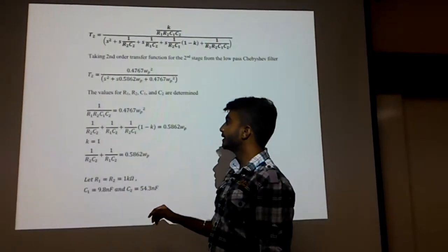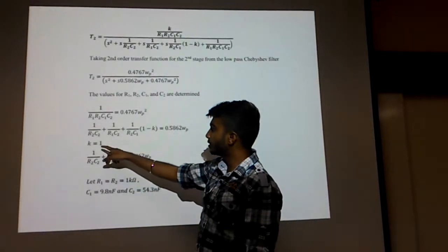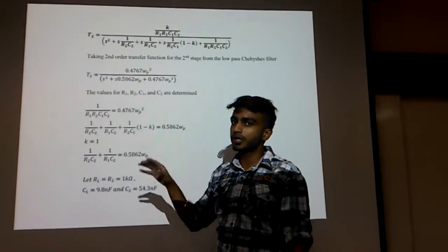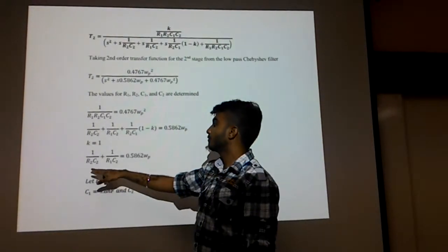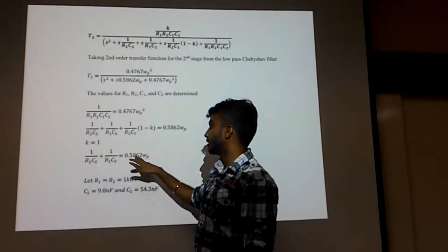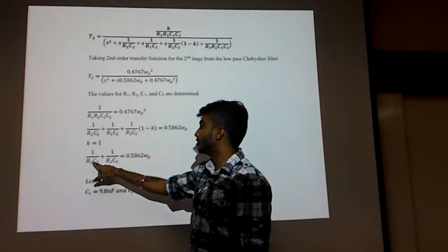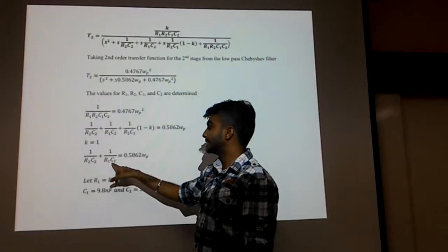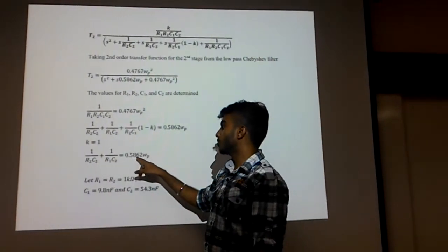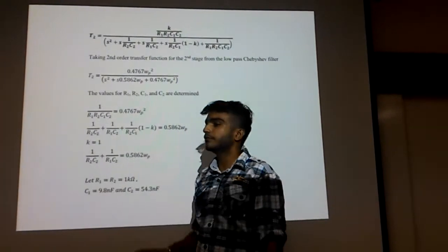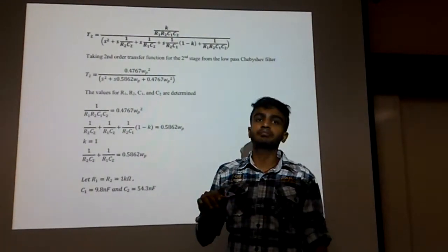So what we are going to do again is, we substitute k equal to 1, because k is the number of order. Now we are talking about the first order, we will get to know that we will get such a value without substituting R2 and C2. So the value is 0.5862 Vp, and now we remain the R to be the constant all the time.